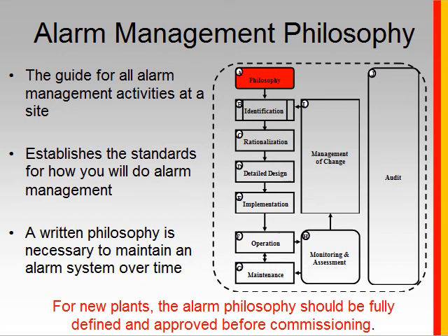What goes on here is the creation of an alarm management document called the philosophy document that will define the standards for how a plant or site will do alarm management throughout all the life cycle stages. So that means it'll define what rules you'll use to prioritize alarms, potentially what colors you'll use in the HMI, and all that kind of good stuff.